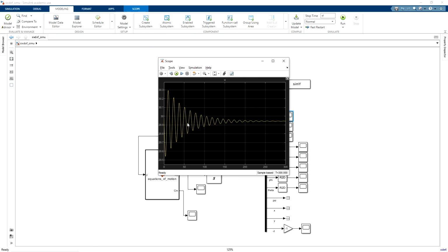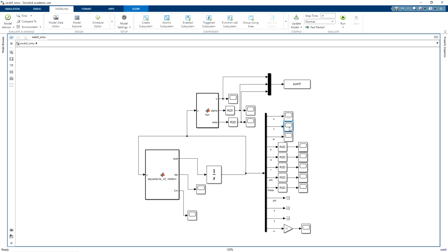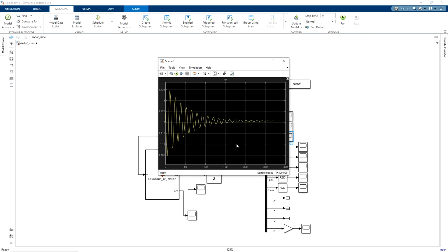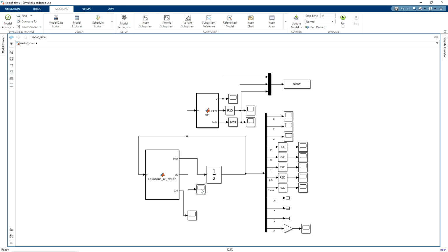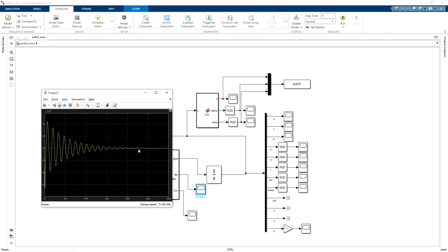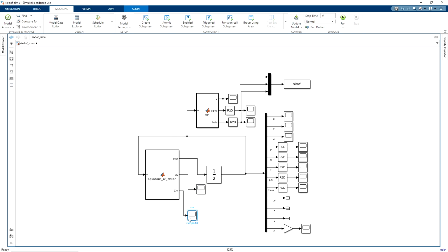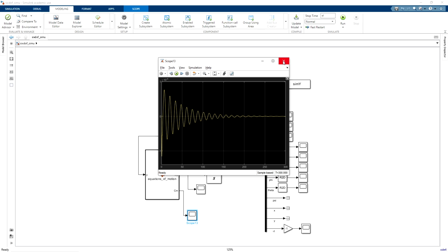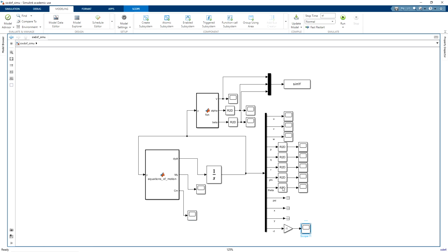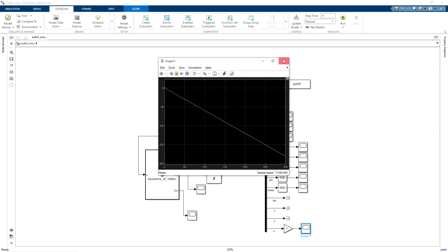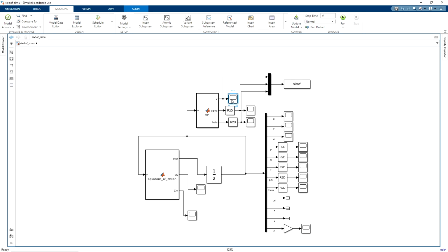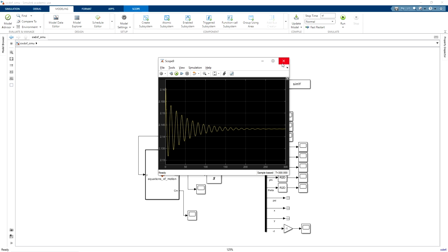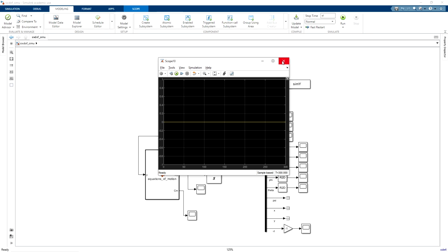This is the forward velocity, which should be around 30 meters per second. Side velocity should be 0 and small w should be around 1 or 2 meters per second. Yeah, it is around 1 meter per second. And this is the total moment about the y axis, which is going to 0 after a certain time. And this is the coefficient of moment. And the altitude, it is actually decreasing. All right. And this is the total velocity v, which should be around 30 meters per second. Alpha should be around 2 degrees. Yes, it is 2 degrees. And beta should be around 0.